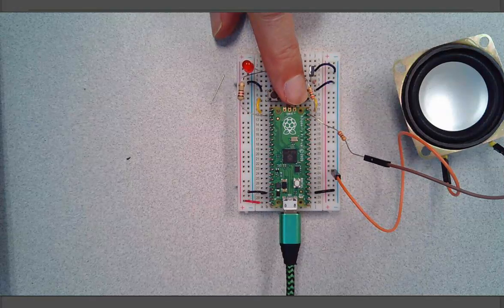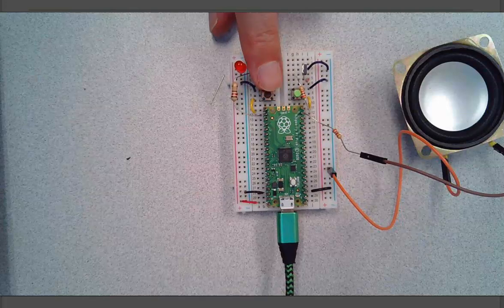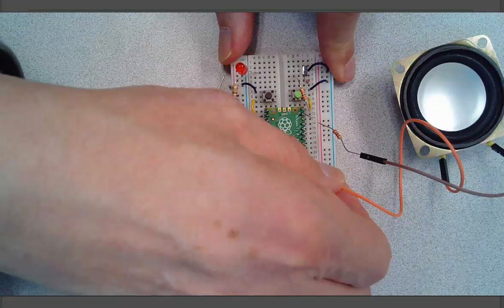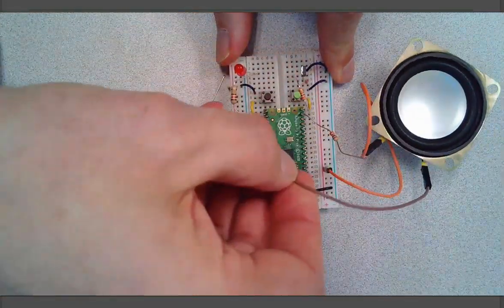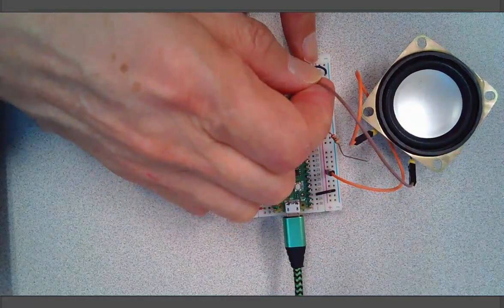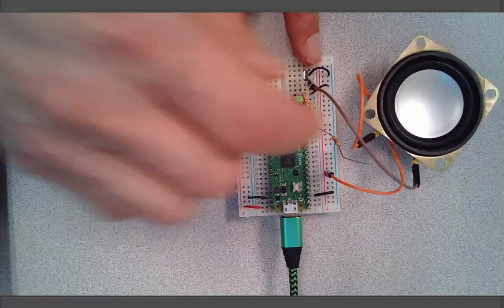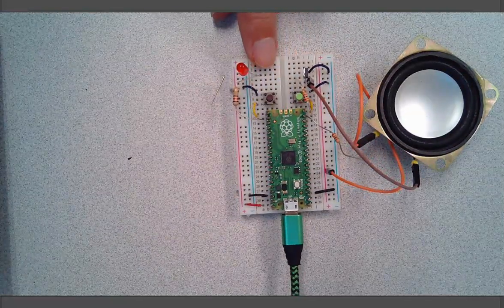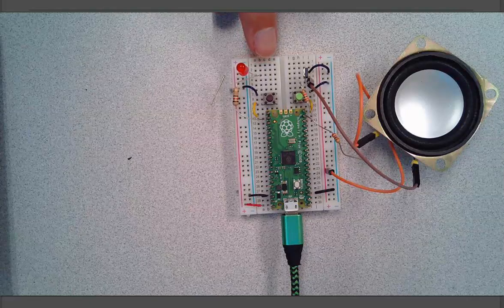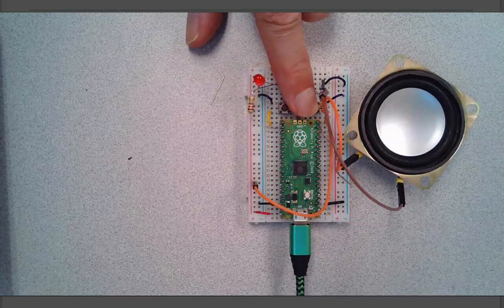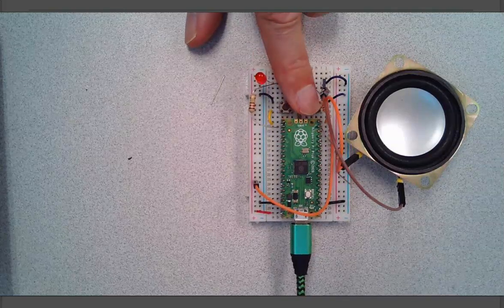You might be able to hear that. It's really quiet. Well, the problem is the microprocessor can only do 10 milliamps. If I add a transistor, that's this puppy right here, I crank up the power. So now instead of doing 10 milliamps, I can now do 1 amp. Maybe. A lot louder. So that's what transistors do.